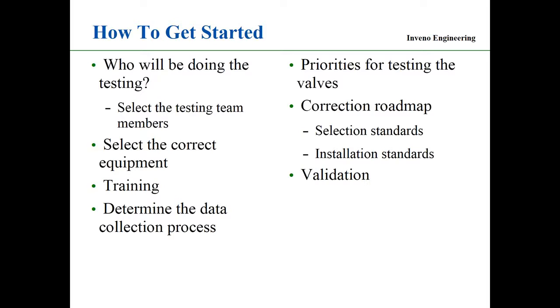Years ago, we used to use screwdrivers a lot. It wasn't too safe because you got too close to the valve, it could be extremely hot, burn your ear. Safety. So today we don't have to do that, but we want to use ultrasonic equipment. Training: what training is required to do the task? Determine the data collection process, which I'll be talking about. Where do I collect the data? How do I collect the data?